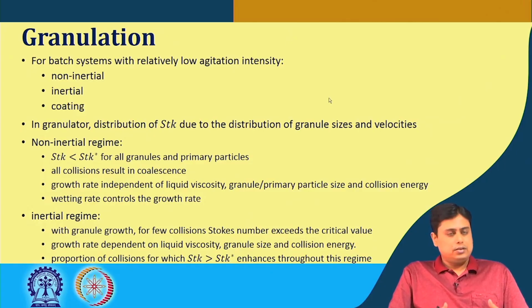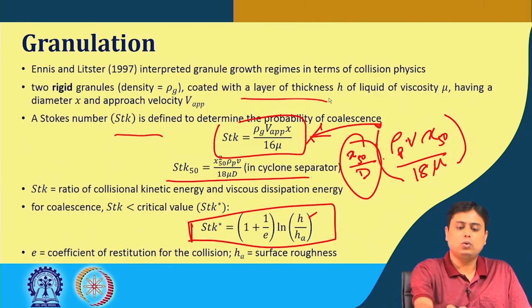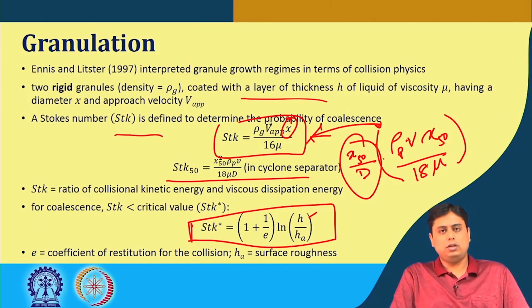On the contrary, in this inertial regime, as the granules grow, a few collisions of these granules have a Stokes number that exceeds the critical Stokes number. Because if we look at the expression, we see the Stokes number is directly proportional to the diameter.